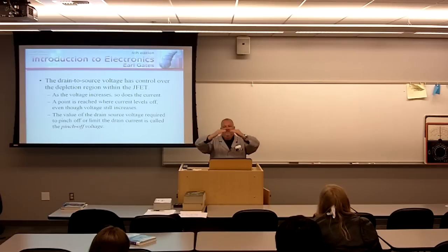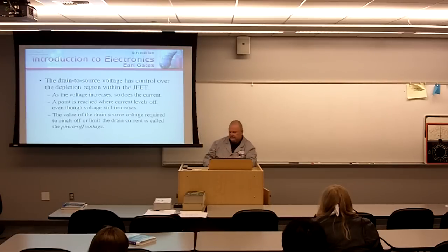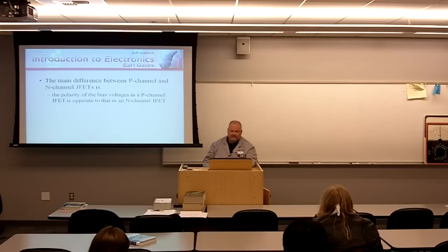But then what's going to happen is this. Voltage will increase, but current's going to remain, because this point right here is the pinch-off voltage. We increase voltage, but yet current does not increase. Again, you want to find that value in the data sheet.